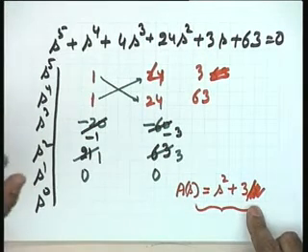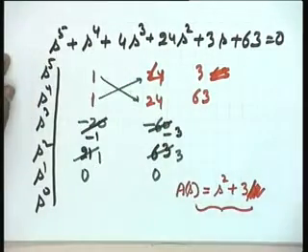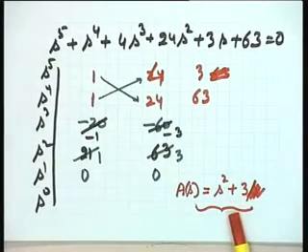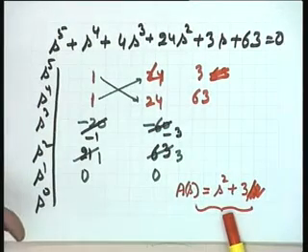The remaining roots could be examined in two ways. One, you divide the total characteristic polynomial by this auxiliary polynomial, so you get the remainder, and you apply your Routh array formulation on the remainder polynomial.